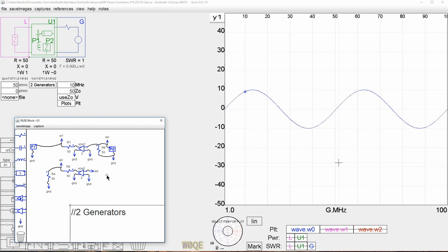And sometimes the lines go through other components and stuff. And if you want to control that so that the circuit looks a little more tidy, you can create points, which are like labels. So label W0 here connects to W0. It can also be used in a plot command or anything else, but they connect together. So there's effectively a line here to here.